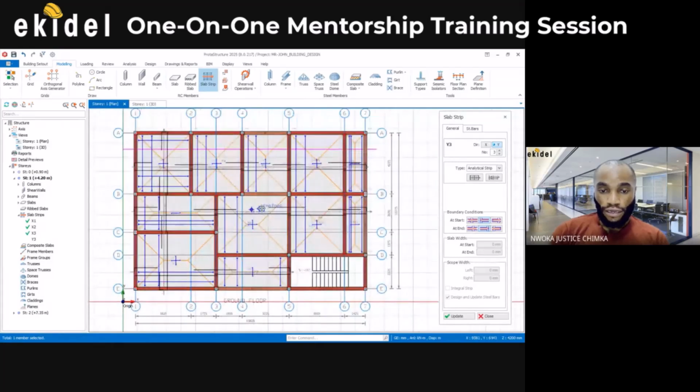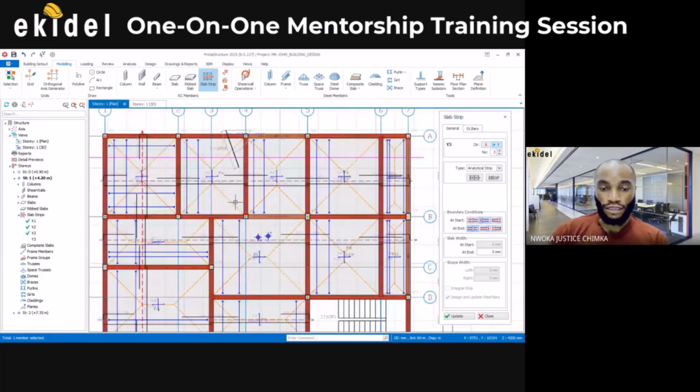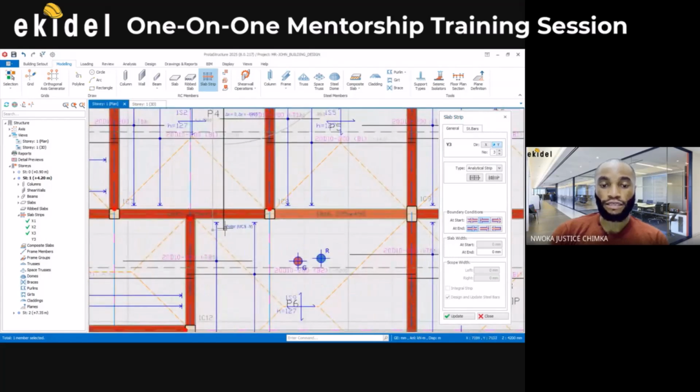Now, I want to cut through this panel. Then later, I'll come and cut. Okay, let me cut this one now. So I want to cut this now, beam to slab. So I'll come here, change the end to slab. I'll come here, click on this, and then pass through the slab, and then click here. So I have that now.